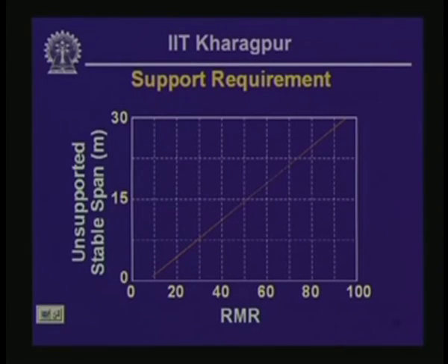Now, support requirement is an issue that needs to be tackled. It becomes apparent that in a jointed rock mass you have to support the possible unstable blocks of rock around the tunnel opening. So, assessment of support requirement is another issue tackled by engineering geologists and tunnel designers.